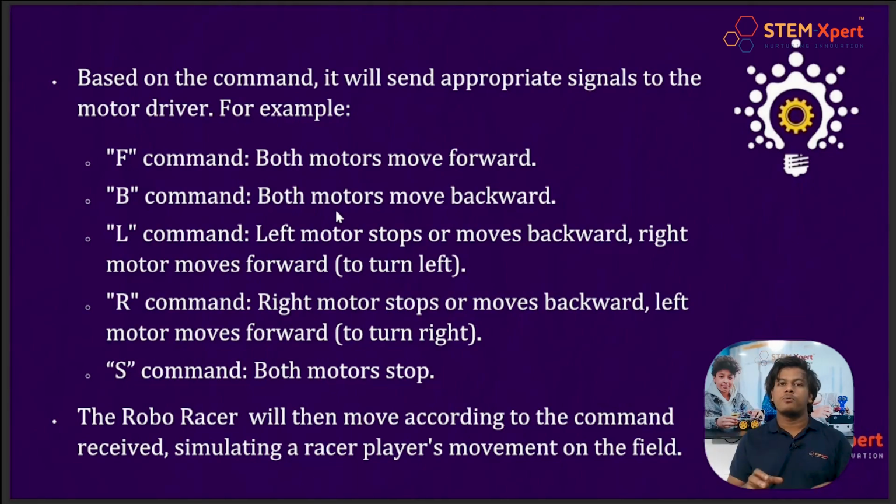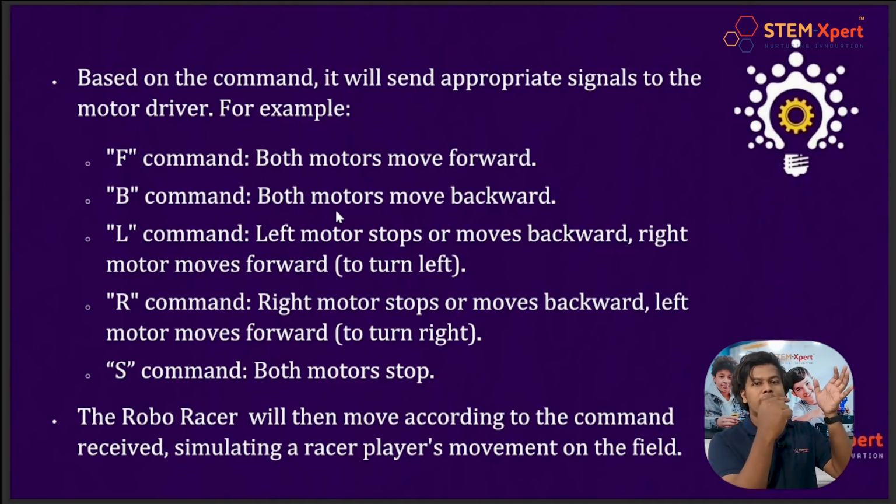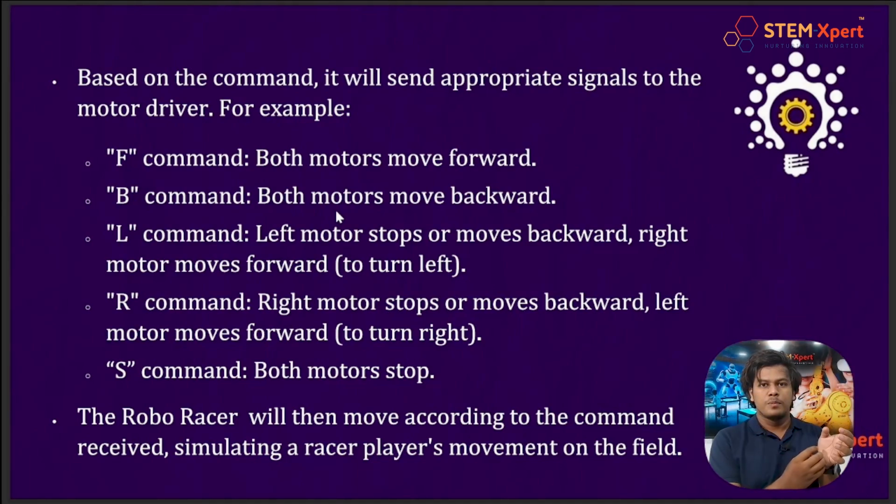And letter L stands for left. Of course, the robot has to move left. So whenever I click the button called L or the left button, the app has to produce the command L, and the board has to receive that command. Whatever is inside the bracket will start to work. So inside the bracket, we will be doing the coding for making the robot move left a little bit. I'm gonna show you that.